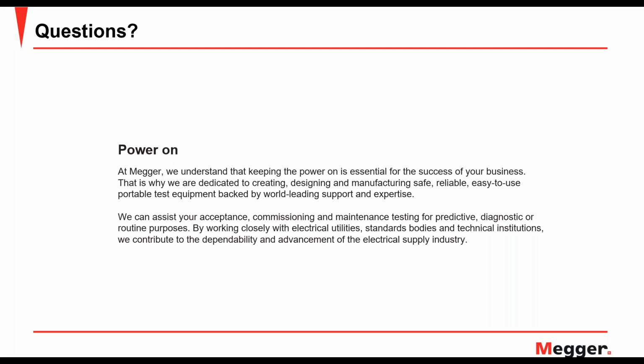There's such a thing that's called magnetic viscosity. Basically, it's a situation where the magnetization level of the transformer's core is varying with time. And when I'm talking about time, I'm talking over days or weeks. It's a phenomenon that happens anytime a transformer is de-energized, for example, or energized, it can cause a slowly varying magnetic change to take place in a transformer.